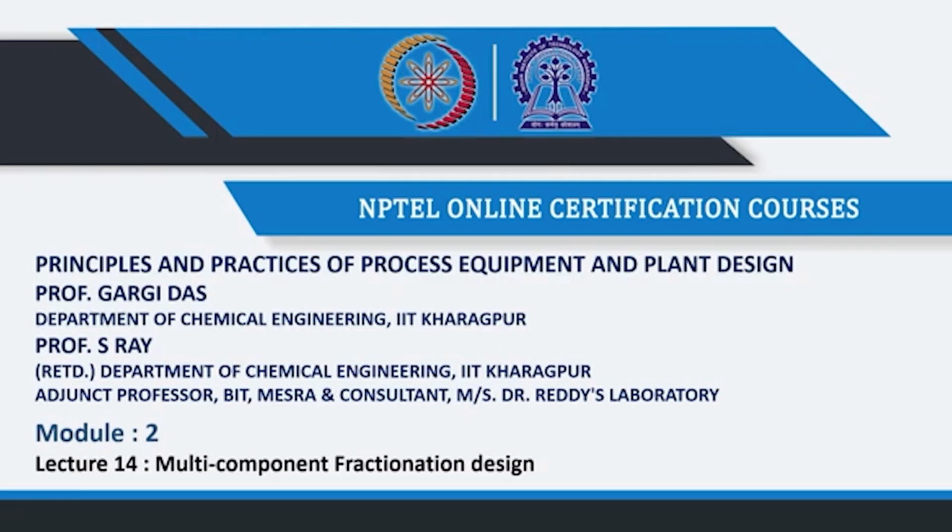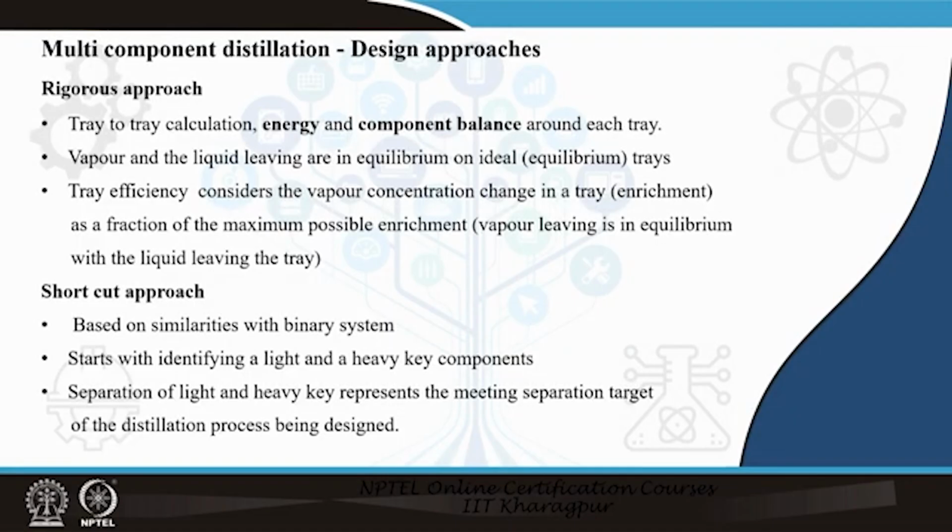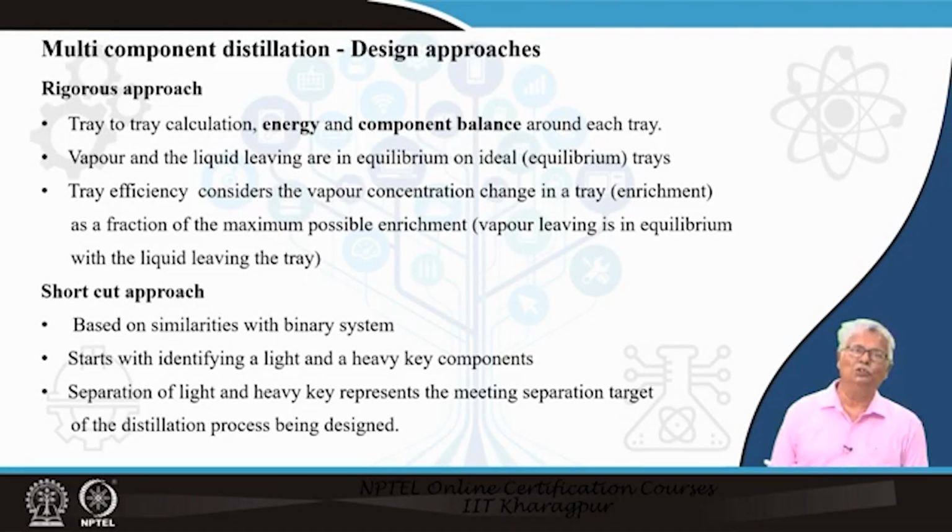I am going to start today's topic, which is multi-component fractionator design. Well, you can call it a fractionator or a fractionation system, whatever it is. To start with, we definitely have to remember that we have covered the binary system distillation design already. Now, the first thing that we have in our mind: there are two approaches to multi-component design, which is also certainly applicable to binary system designs as well.